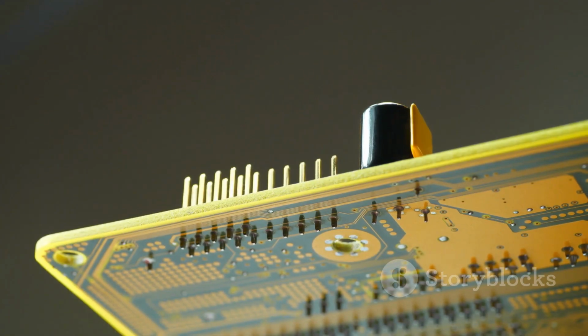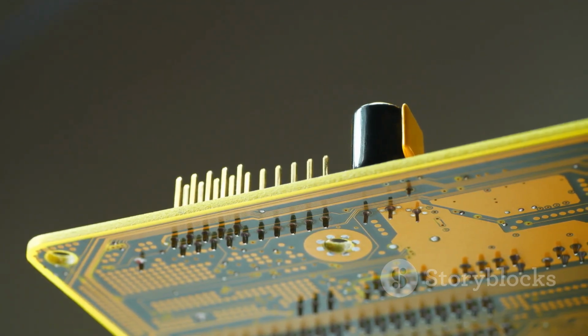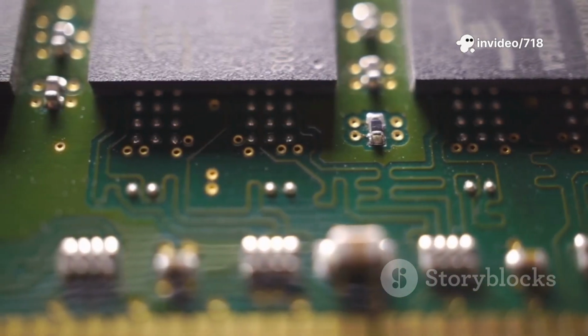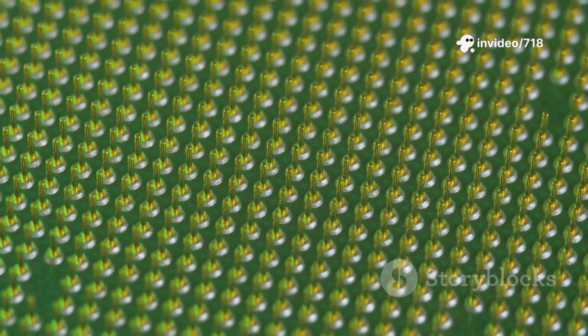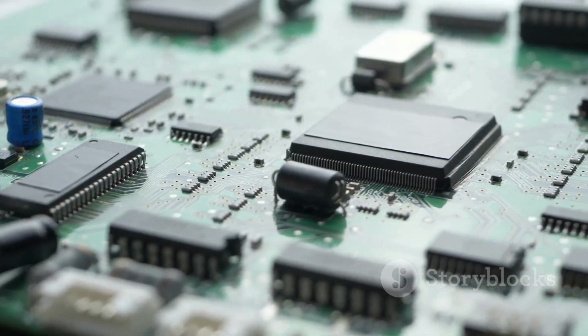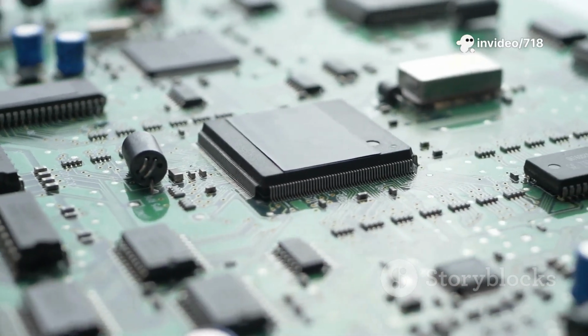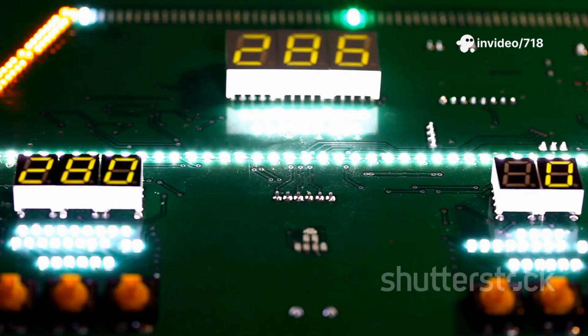At this point, the tiny electrical charge from each capacitor in the row spills out onto its bit line. This is a crucial moment. The charge is so minuscule that it only changes the voltage on the bit line by a tiny fraction. A specialized, highly sensitive circuit called a sense amplifier then detects this minute voltage change. It cleverly figures out if the change means the capacitor was full, a 1, or empty, a 0.